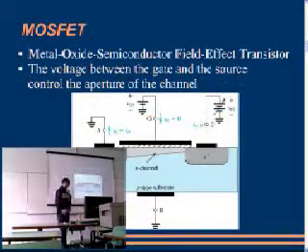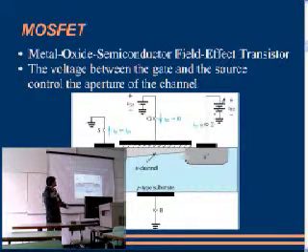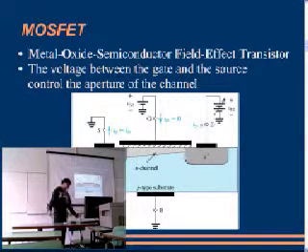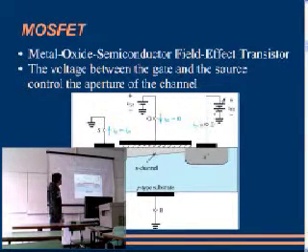We have basically two kinds of transistor: the MOSFET, the field effect transistor, and bipolar transistors. In semiconductors with a heavy density of transistors, the most used is the MOSFET type. Why do they use the MOSFET type? Because you can make MOSFET transistors smaller than bipolar transistors, and they are cheaper to make.